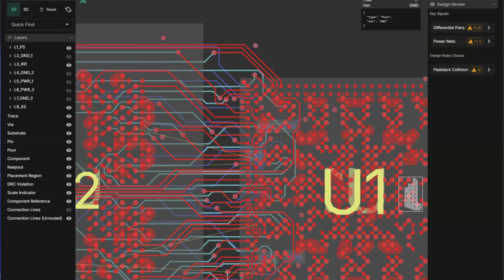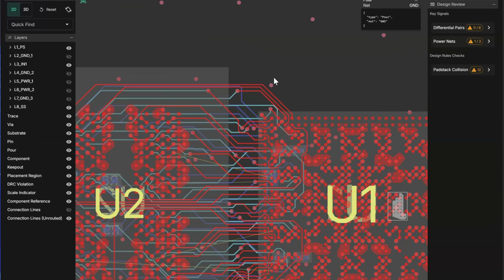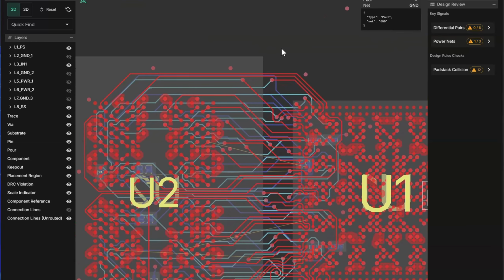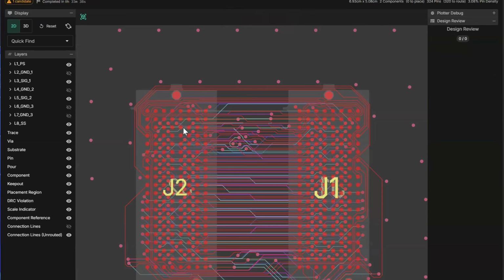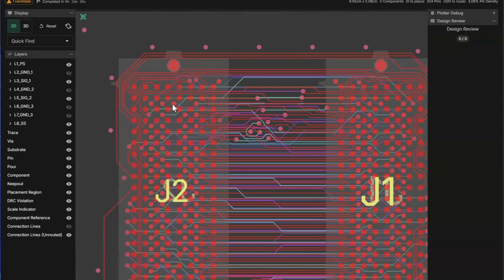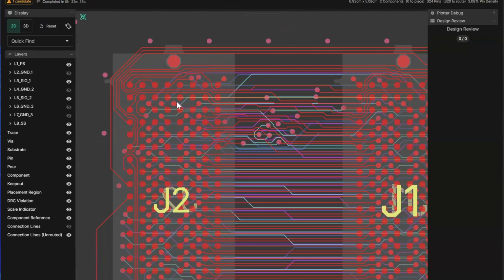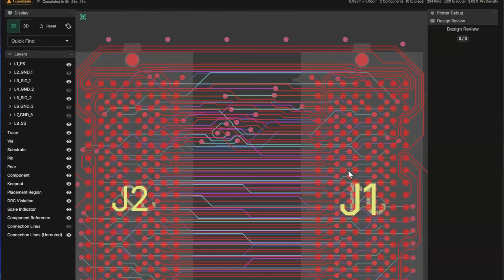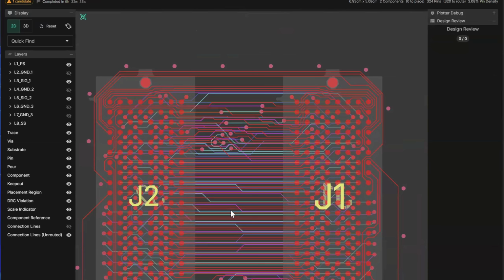This is useful not just for more traditional BGAs. We also found it quite useful for backplane connectors. We see customers using much more massive giant grid connectors. And the same kind of strategy works really nicely there too, where we can fan out and escape each one of these, and then it makes it much easier for us to get these hooked up and routed.